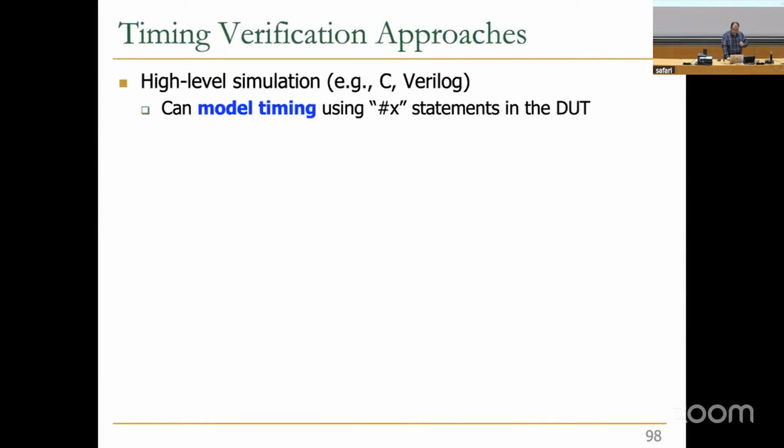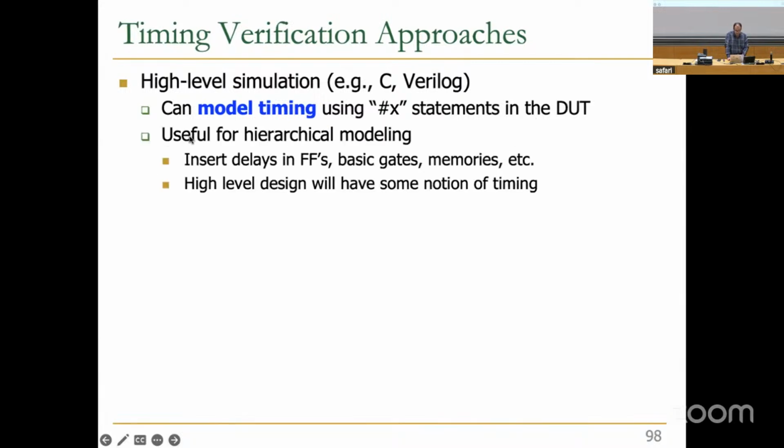So for timing verification, we have approaches. We can also do it at high-level simulation, and because we can model timing using this notation, #X statement in the device under test, which is actually useful for hierarchical modeling. We can insert delays in flip-flops, basic gates, memories, etc. I also briefly mentioned that in cell libraries that you have, there are delays of different cells.